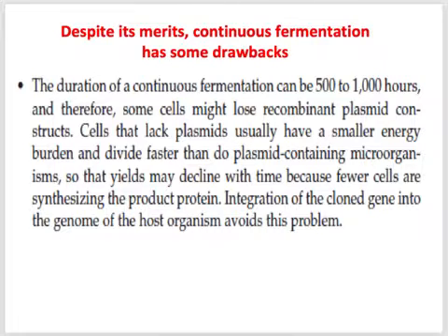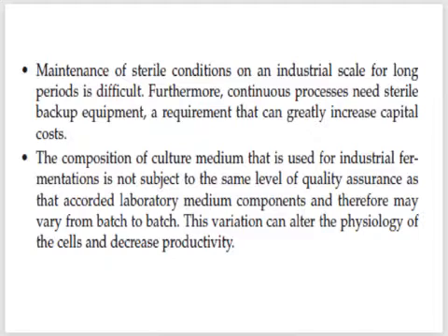Another thing, continuous fermentations are more prone to contamination in comparison with the batch fermenter, because batch fermentation happens in a closed system. We put everything there, the raw materials, the organisms, we close it, and we just turn on the fermentation. It keeps going on until we stop it. We don't add anything, we don't harvest anything from there, so there is less chance of contamination here.